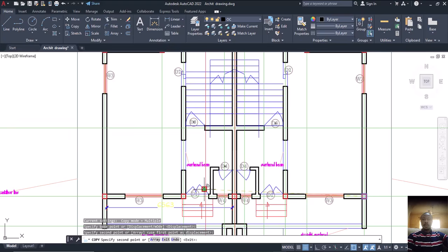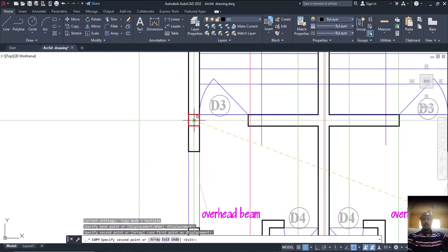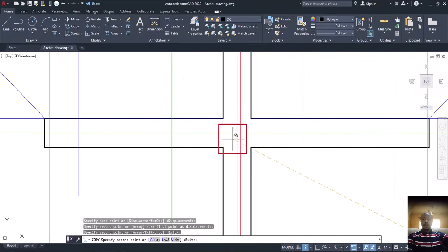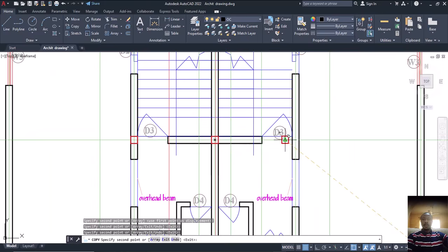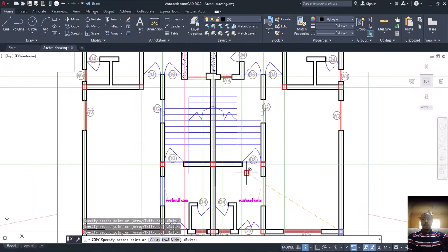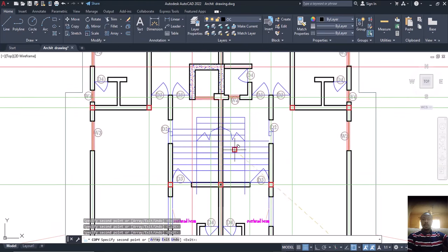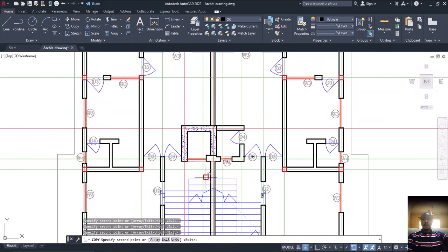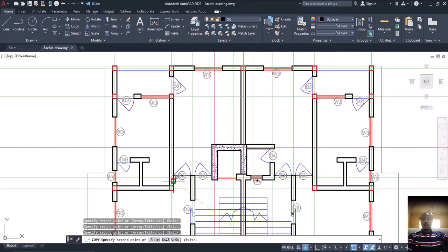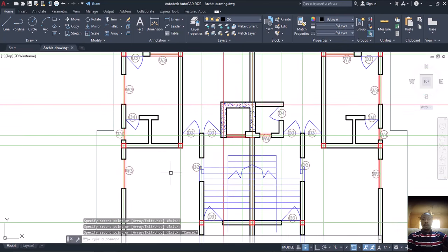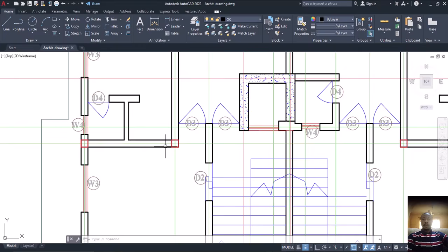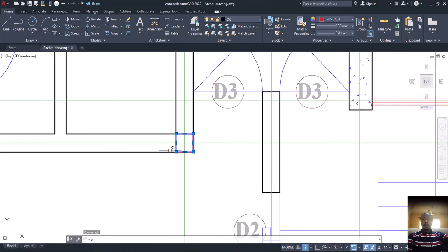So also if I look at this place now, around this place I'll need to fix one here so that I can have a panel here, isn't it? So around this place, this staircase, come here, put another one here for now, and also this one here for now. Okay, so now remain this place. If I have this place now and I have this place like this, is that okay? So something must happen around here, isn't it? So now it then means that, let's now reason it out. It then means that I will definitely need a beam that will run from here to this place, because if I put a column here, let's do it, it will be too close to each other.